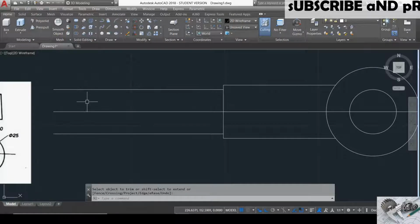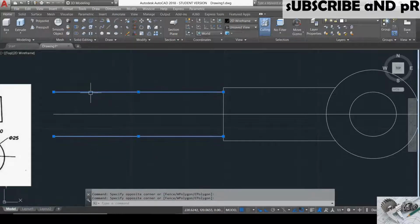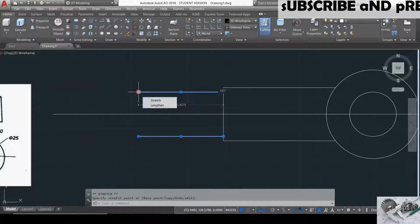Let's stretch these two lines. Select the two lines, select the end points, press the shift button and then select another end point, and then stretch it at the midpoint.